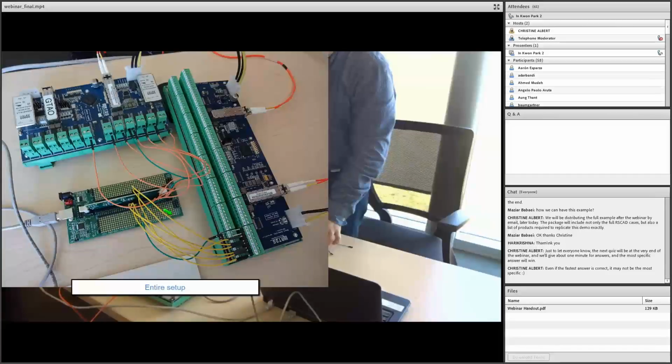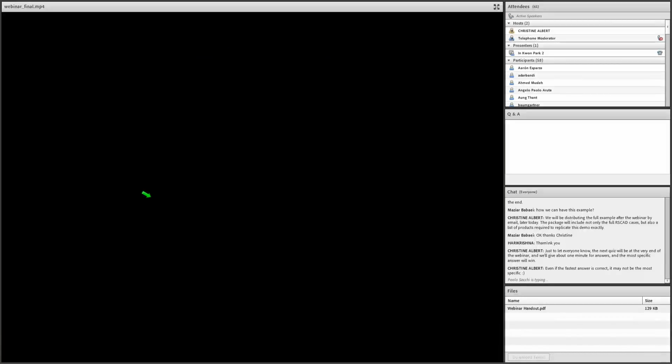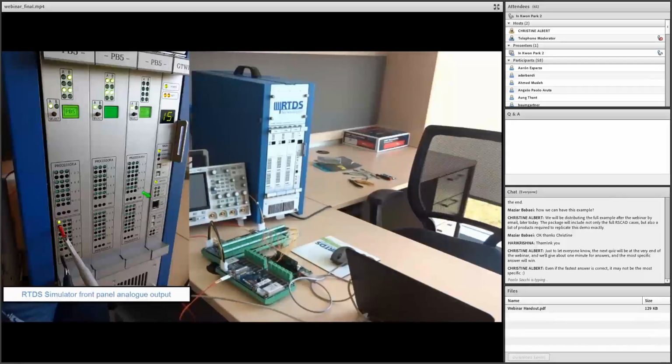As you are already familiar with, the USB port power spec is 5 volts and 500 milliamps. So the total amount of power you can get from the USB port is about 2.5 watts. But because this DSP is not consuming too much power, the USB power supply is sufficient to run this board. So no worry about having an external power supply for the controller. So now everything is ready.